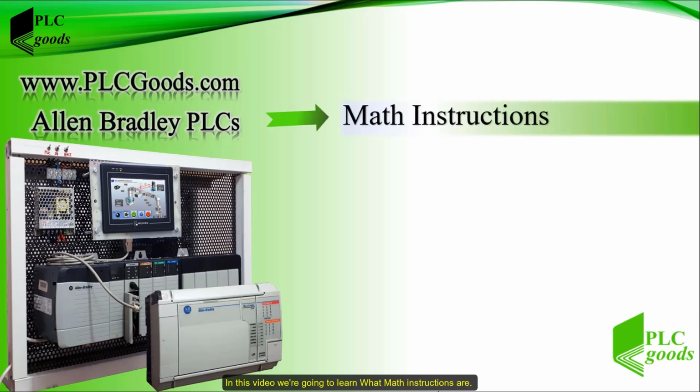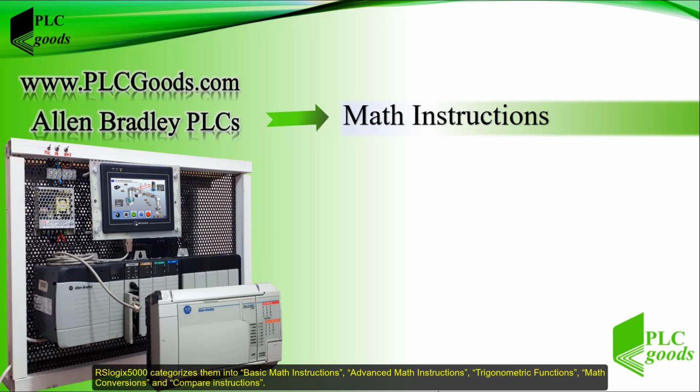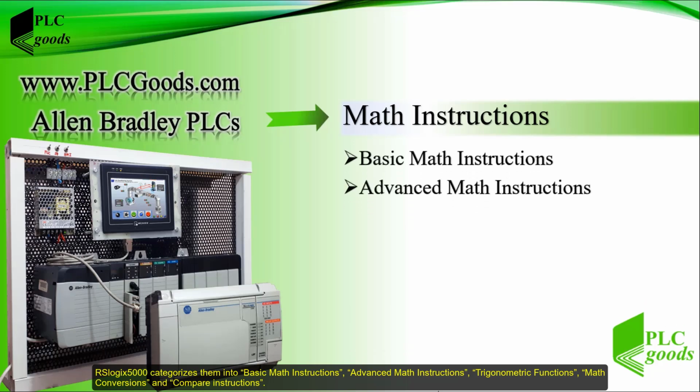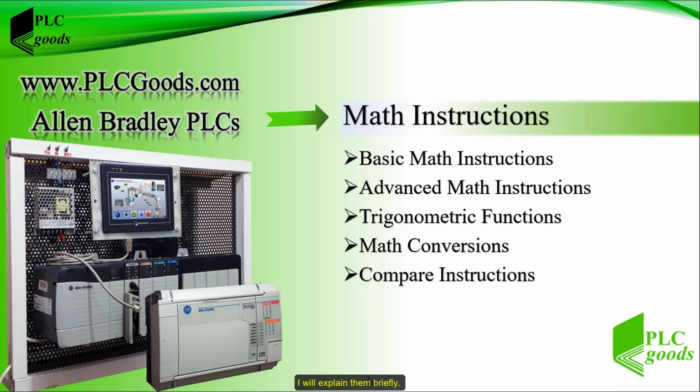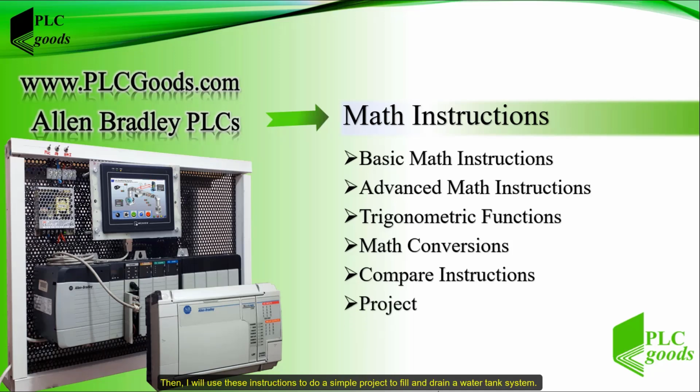In this video we are going to learn what math instructions are. RSLogix 5000 categorizes them into basic math instructions, advanced math instructions, trigonometric functions, math conversions, and compare instructions. I will explain them briefly. Also, I will show you how the help window of RSLogix 5000 can help us learn each instruction. Then I will use these instructions to do a simple project to fill and drain a water tank system.